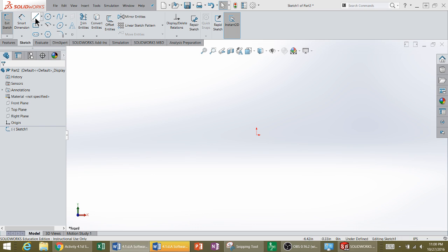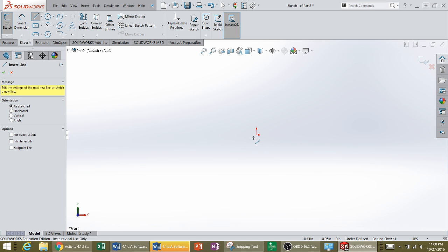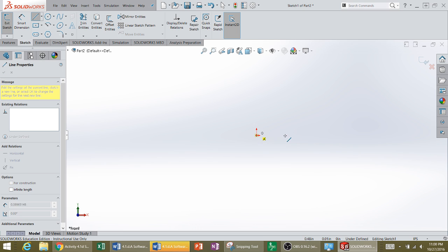Now for now it's not real important, but every time we make a sketch in SolidWorks, we want to be sure that we orient it relative to the origin. And for now I'm going to start at the origin. And you'll notice that I get this little glyph, the little yellow mark. What that's telling me is if I click once, release, and then move my cursor, I will start to drag this blue line out. Now notice as I approach the horizon, I get a horizontal yellow glyph. So I'm going to sketch the bottom of my L. So I'm going to go ahead and sketch, drop that.